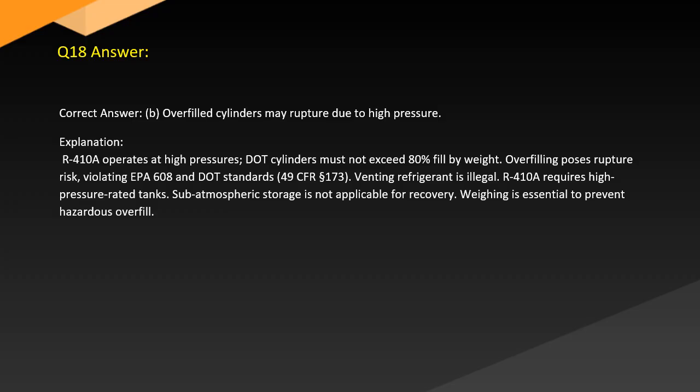Venting refrigerant is illegal. R-410A requires high-pressure-rated tanks. Subatmospheric storage is not applicable for recovery. Weighing is essential to prevent hazardous overfill.